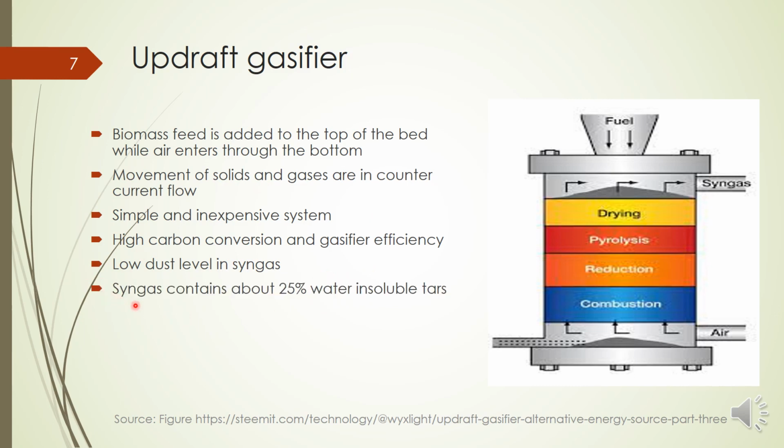But the problem is the syngas will contain about 25% water insoluble tar. So tar formation is an important thing we have to face while designing a gasifier. The tar is a compound that is insoluble in water, and is in liquid state. So once the tar is formed, it will block the passage of gas, solids, etc., and ultimately it will affect the performance of the gasifier.